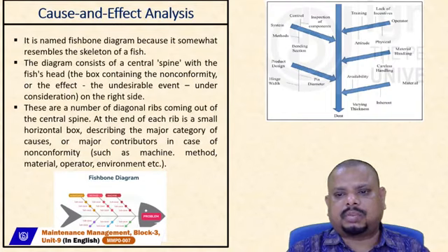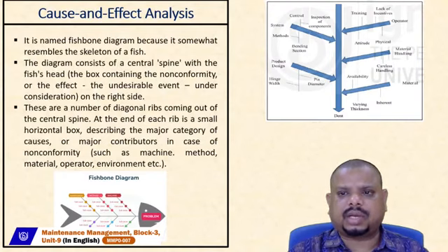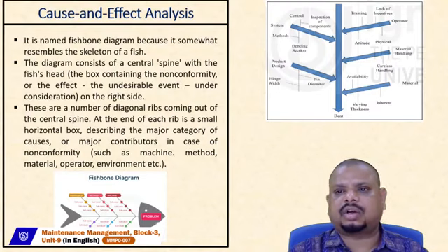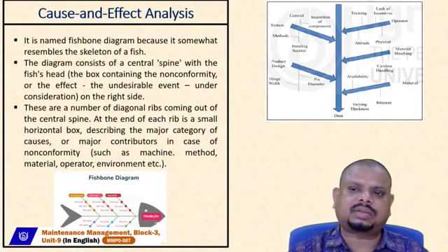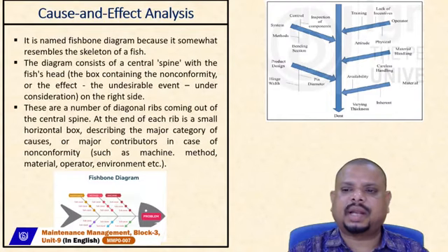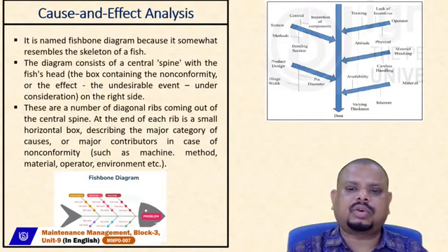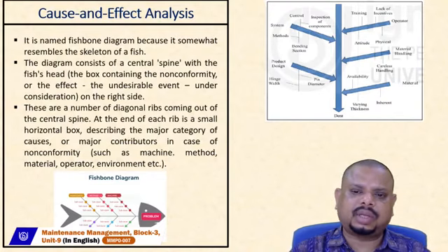Let's take an example of automobiles which have dents. So the dent is the problem. In that case, you have to consider operators, material handling, raw material, product design, and systems. In the case of operators, we have to consider training, lack of incentives, attitude, and physical factors. Similarly, in material handling, careless handling is the cause. Next is material, where availability and variation in thickness are inherent. In product design, you look at pin diameters and hinge width. These are the technical things included to repair the dents.